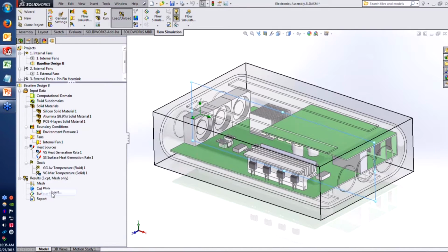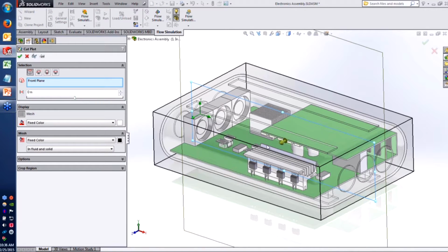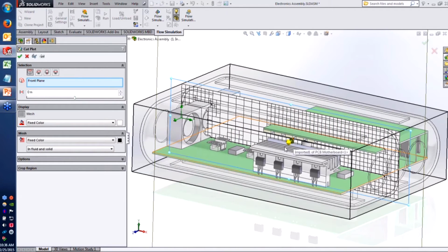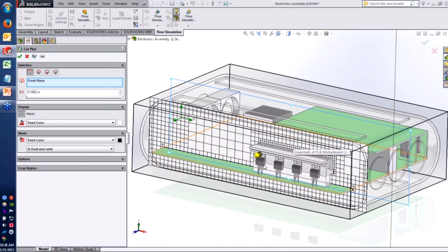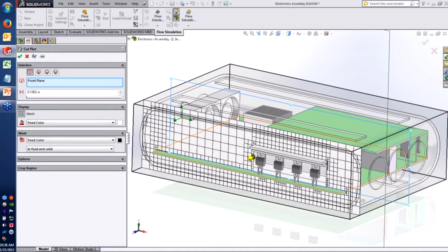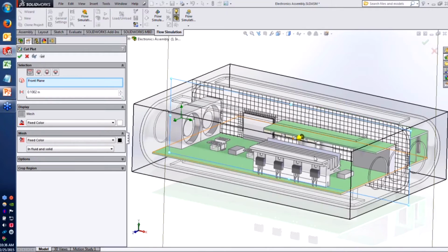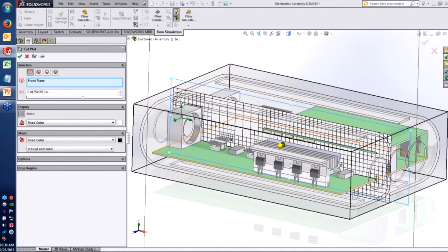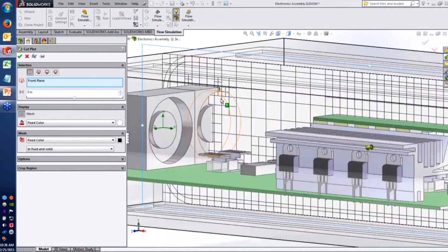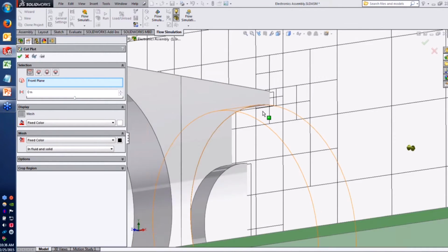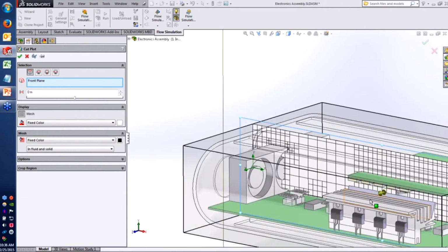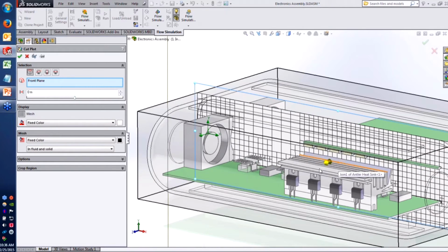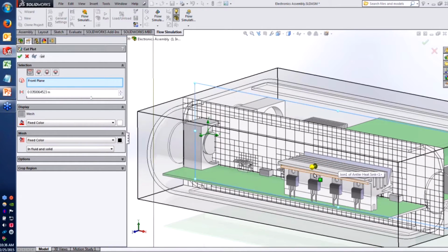So the mesh has been generated, which we could look at here in a nice little preview. If we sweep back and forth, as you can see, it's basically an XYZ grid that's been subdivided, and we have this unique, what we call partial cell technology, to account for the correct shape of the geometry, even in areas like this where it's a little curved or it's not matching up to the boundary of the cell properly. We will actually be able to detect where that solid surface is within the cell and split the cell up there properly so that the boundary layer is calculated the right way.